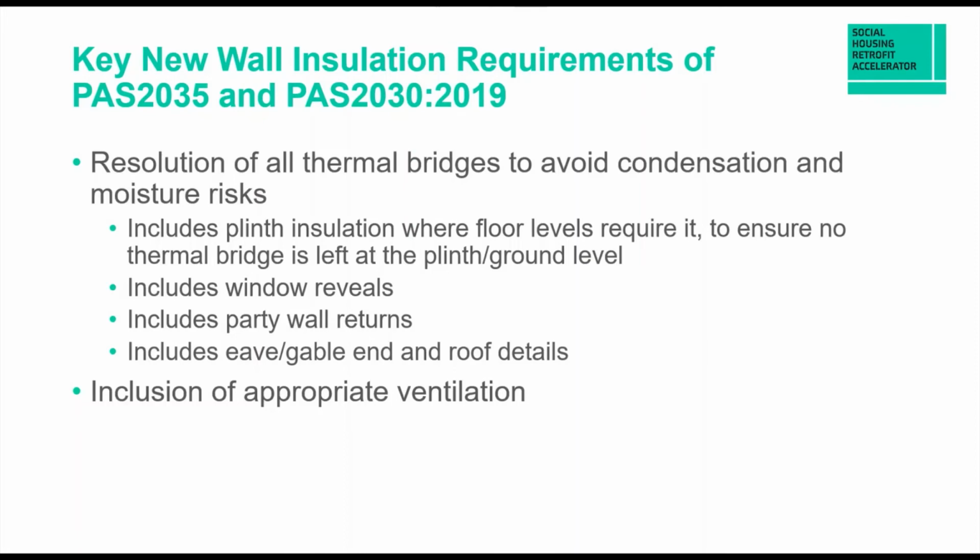So this is quite an important thing to consider, because if you are in a situation where you're going to have to excavate around the outside of a property to be able to insulate down into the ground, that is a lot of work. It's a lot of groundworks. It's quite expensive. It's quite time consuming, and it's going to involve things like moving sewers away, moving drainage away, moving potentially gas lines away. So you will have other things that need to be dealt with below the DPM, DPC, and those can be quite a significant cost if you haven't kind of planned that in advance.